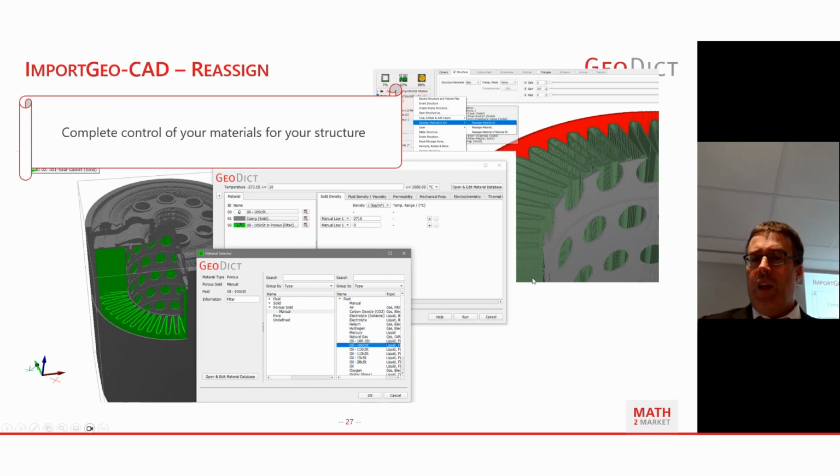In this case here, I want to replace the pleat. So the casing can just be one material. Everything which is not the filter itself, I can put to one material. So in this case here, we have just one casing left, and the filter element is the green one down there. Actually, I think in the next one it is a bit brighter green. If we are already here, we can set the material of our filter to be a porous medium with oil inside. That's just because this filter was an oil filter by design.